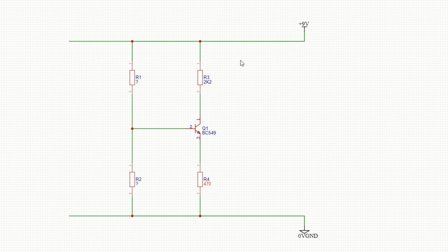So that gives you 7.5 volts swing. So saying roughly 3 to 3.5 volts across that resistor gives you the best range. And for 3 to 3.5 volts you need 1/5 of that across that resistor. So 0.6 to 0.7 of a volt. The transistor will also drop 0.6 to 0.7 of a volt in its base emitter junction. So that means the base wants to be at about 1.2 to 1.4 volts.